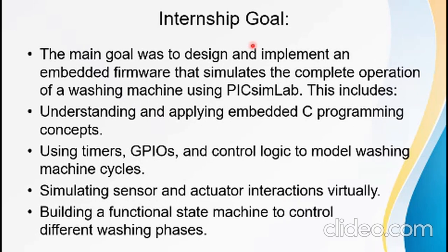Now let's move toward the internship goal. The main goal was to design and implement embedded firmware that simulates the complete operation of the washing machine using PICsimLab. This includes understanding and applying embedded C programming concepts using timers, GPIOs, and control logic to model washing machine cycles, simulating sensor and actuator interaction virtually, and building a functional state machine to control different washing phases.